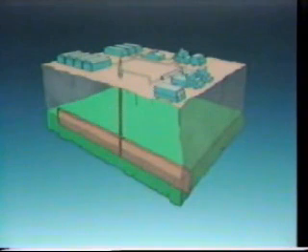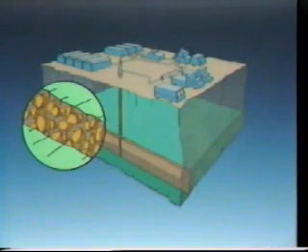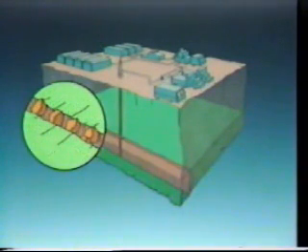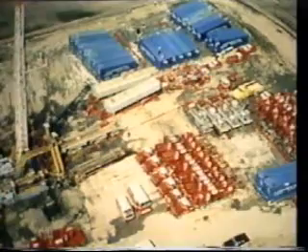As the fracturing fluid is pumped into the fracture, extending it further from the well bore, a proppant material, usually sand, is carried along in the viscous fluid. When the pumping stops, the frac fluid flows back into the well bore, leaving the proppant to prop open the crack and prevent it from closing up completely. In this manner, a high permeability pipeline to the wellbore can be created, often extending thousands of feet out into the reservoir on either side of the well.